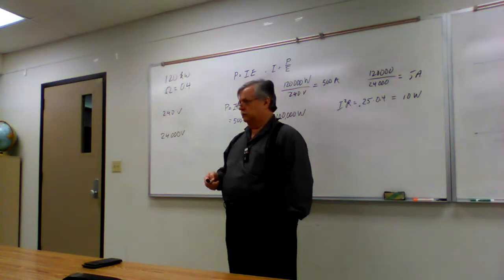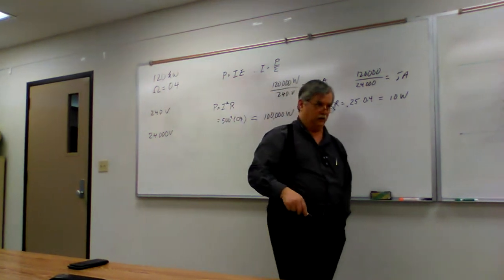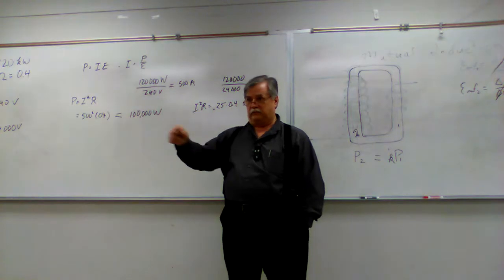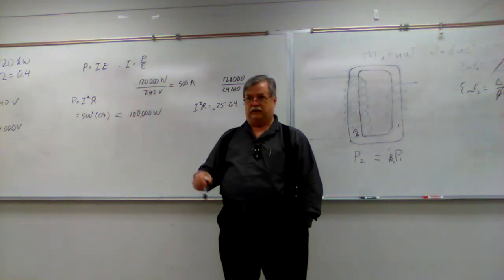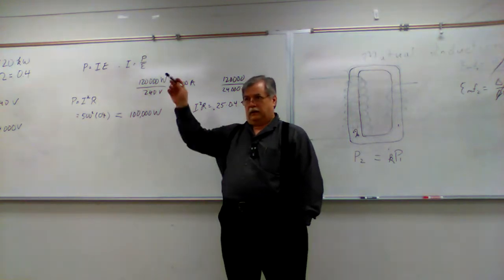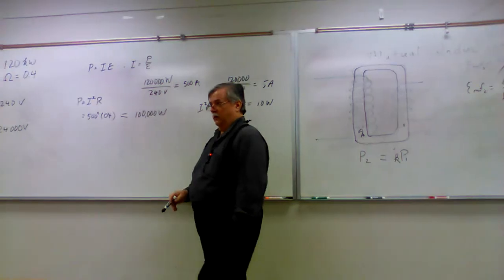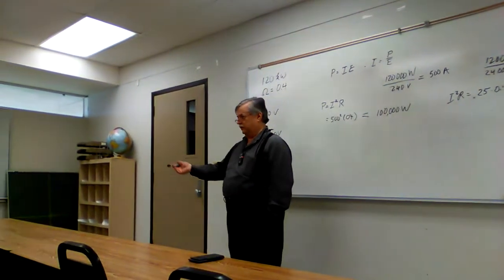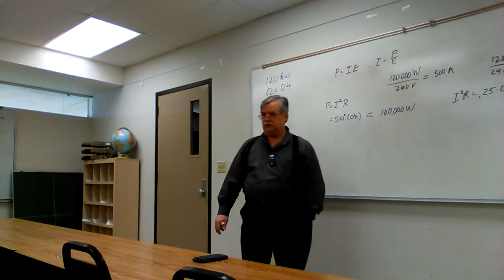That's reasonable. And it gets down to a substation level where they bring it down to like 2,400 or so, that they actually pipe around at the street level, before it gets to the transformer on the pole outside of your house where it's brought down to the 240 volts for your normal mains service into your house.